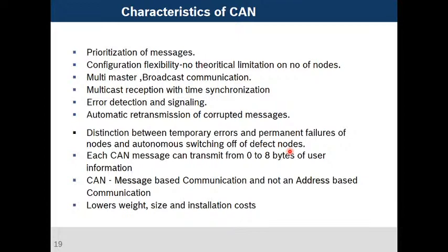If music is playing and you apply the brake, the music should definitely be low priority, and the brake should have higher priority. Only then will the braking be applied immediately, within a fraction of microseconds. That's the reason CAN has a prioritization concept of its own. The CAN ID of the braking system will be higher in priority compared to the music system. That's the way of designing in CAN.